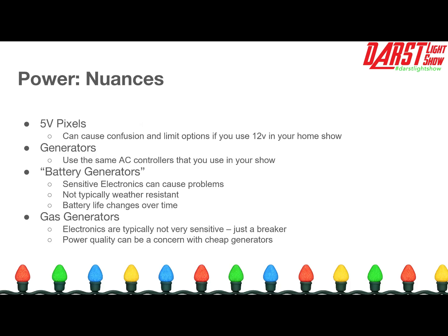Oh, and your battery life reduces over time. So while you might get 2 hours runtime out of it today, if you use it several times, or it sits and isn't maintained well, you might only get an hour and a half when you go to use it a year from now. Gas generators, typically their electronics aren't very sensitive. They'll just have a breaker that could trip, but you could get into power quality concerns with cheap generators that could then cause failures of power supplies or failures of controllers.